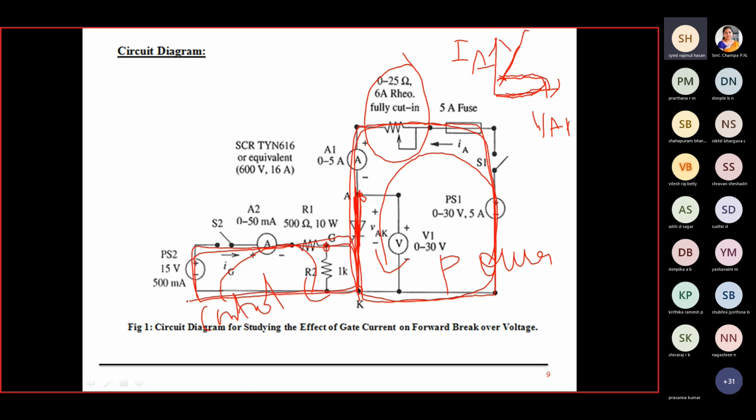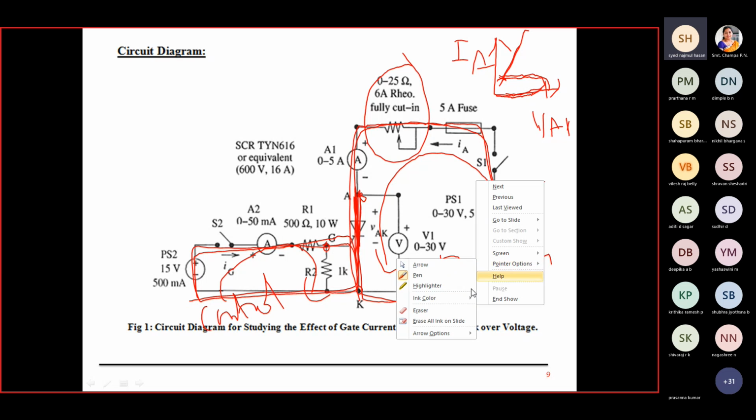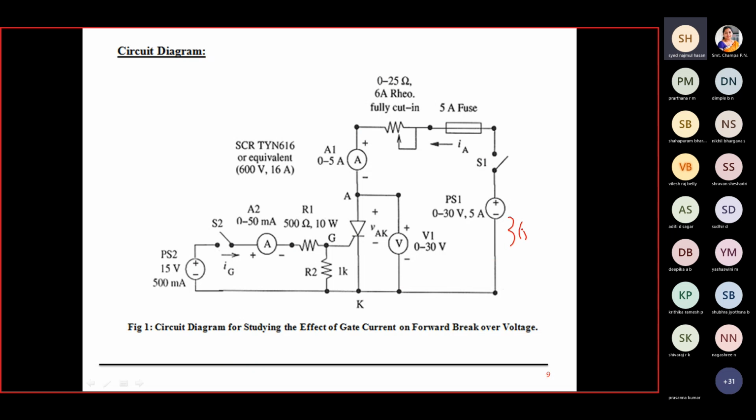The control loop, basically, we give a small voltage for the SCR to turn on. But since we cannot go for a 300 volt DC or a 600 volt DC, they are very hazardous, right? In the lab, we conduct the experiment only with 30 volts. So you won't get shocked wherever you touch, whatever part of the circuit you handle, nothing will happen, because a human being senses shock from 60 volt onwards, not below that. For any electronic gadgets, from 60 volt onward, you feel a shocking sensation. So we restrict to 30 volt and 15 volt here, not more than that.